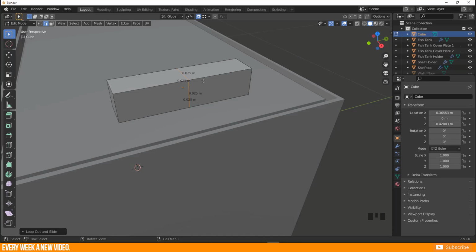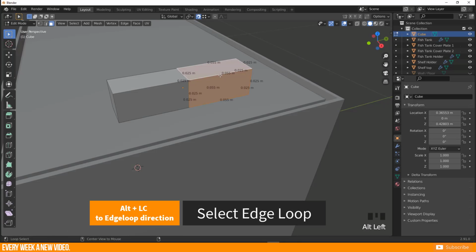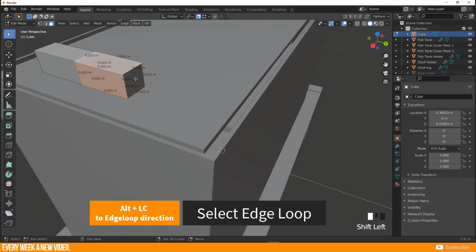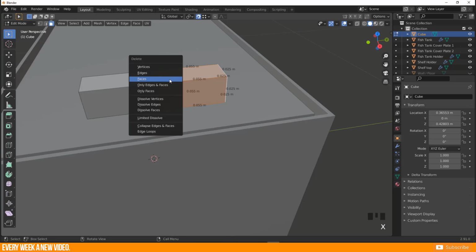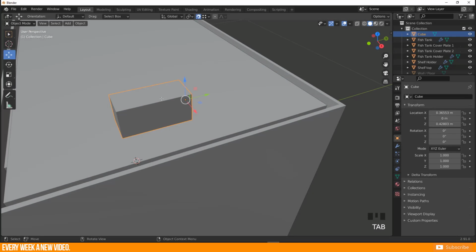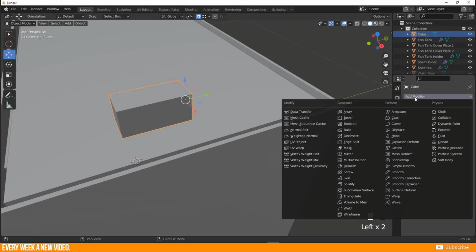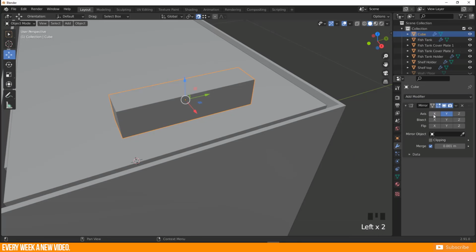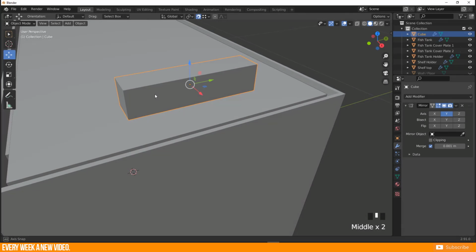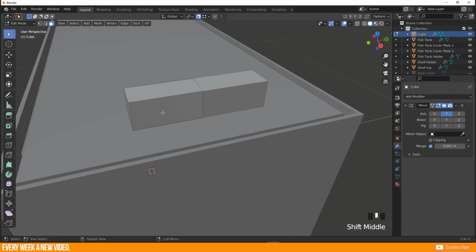Basically, we are able to mirror this. I guess I will do this because this is completely mirrorable. So, okay, then I switch to face selection mode. Select all of this by pressing Alt plus left click. And with Shift left click, I add this face here and press X to delete this. And then I go again to object mode, go to the modifier section and add a mirror modifier, which will mirror this to the epsilon direction. Well, perfect. So go to edit mode, and now I have to just adjust this side and everything will mirror to the other side.